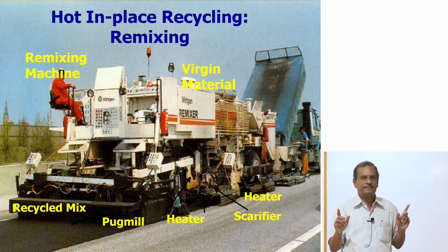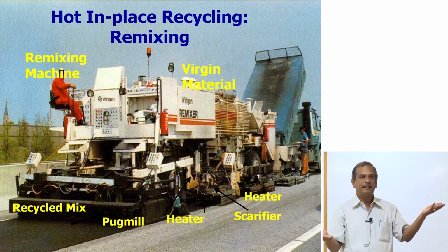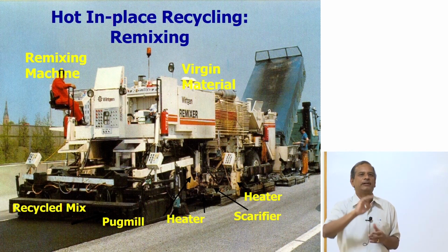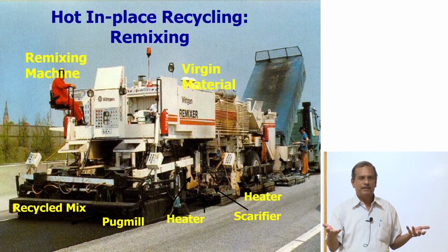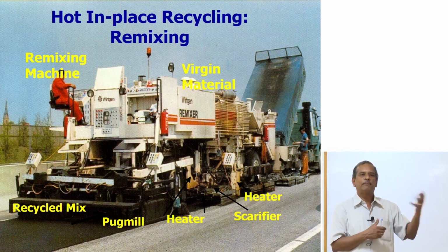Life cycle cost analysis, road asset management, pavement preservation. These are the technologies and techniques that you have to adopt when you graduate. So construction is on one hand, and maintenance is on the other hand. Maintenance challenges are like a doctor diagnosing a disease. You have a road that is deteriorated, for example, the campus roads. The campus roads have deteriorated. These roads were constructed in the year 2009. Now they are 10 years old. Now what should I do? As a civil engineer, you should be able to tell: should I recycle? Should I use a modified binder?